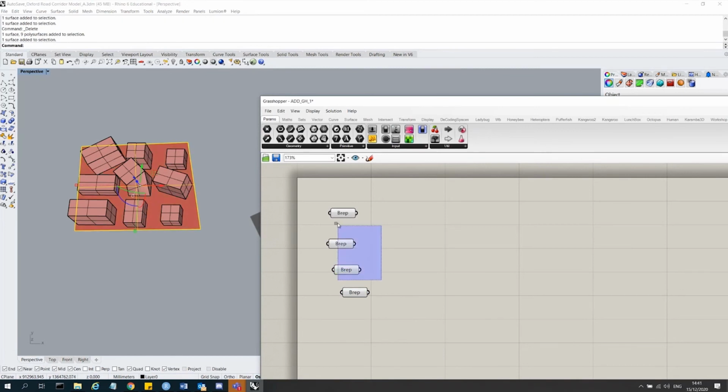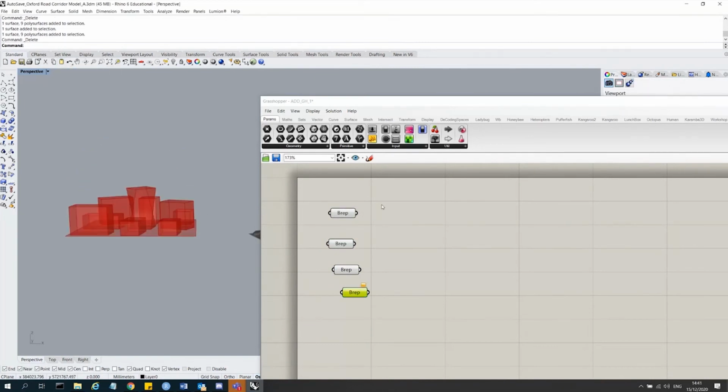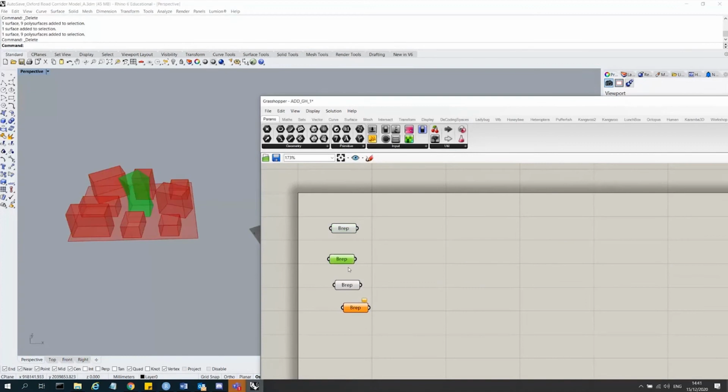Okay, so I've internalized these 3. Internalized meaning saving the Rhino data in my nodes, so they're contained within my nodes. And this one is just referenced. So now if I delete all these and click on this, you can see I already have the geometry, despite the Rhino geometry not existing at this moment because I've deleted it, right? But with this one, it doesn't exist. So you can see one locally defined value, null. I used to reference a geometry, but now it's gone. So that's the difference between internalizing, which we use here, and just referencing something, yeah? So I hope that's clear. So let me delete this. I don't need this. I'll just save this.